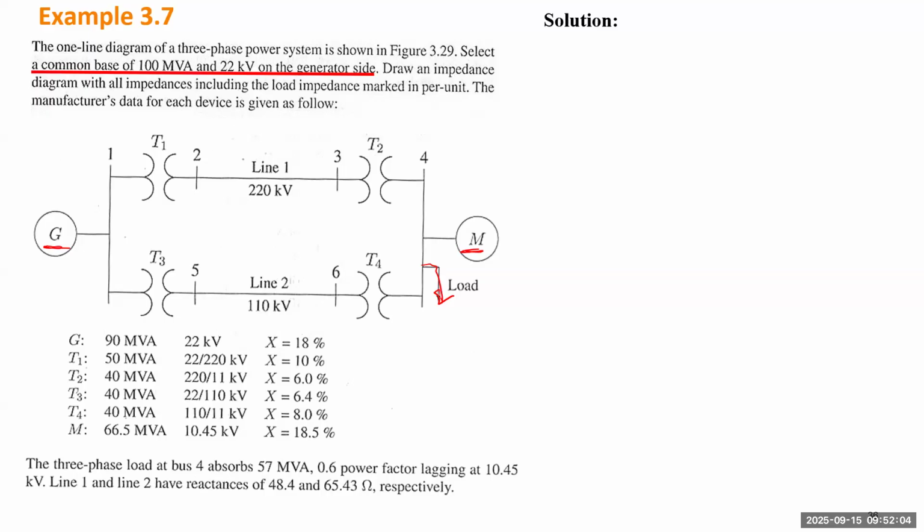There are two transmission paths. One path is at 220 kV, the other is at 110 kV. The generator operates at a lower voltage. Those are the summary of the nameplates from all the equipment. The generator operates at 22 kV, so I need this step-up transformer to change from 22 kV to 220 kV and deliver through this transformer.